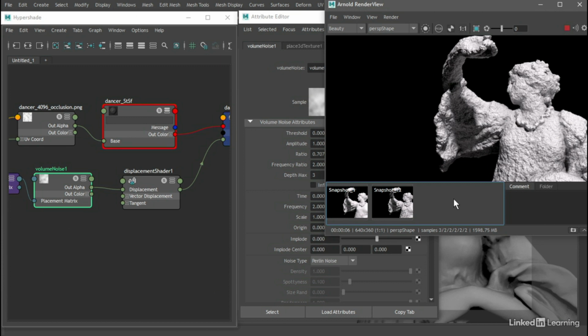As the name indicates, Auto Bump applies an automatic bump map to a displaced surface. It does that in order to resolve surface details that are smaller than a polygon. So we could subdivide the surface and create more polygons, or we could apply an auto bump. And auto bump is the default behavior. Let's see the effect of disabling auto bump.